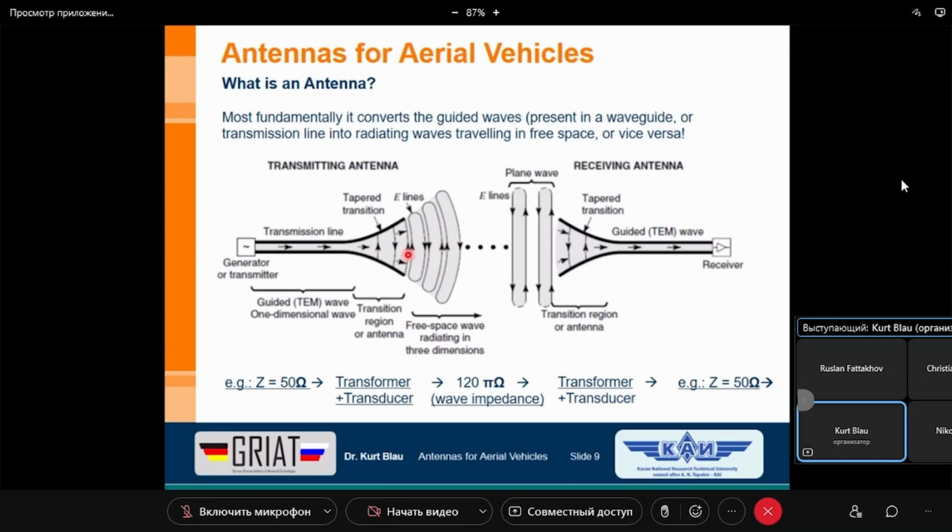1 divided by square root of 2. And this is the voltage. And this we have to, for instance, divide by 50 ohm. And then we have the current flowing in this line here. Then we have to multiply it again by the voltage. You can make a short formula on your paper, and then you can very simply calculate the power.